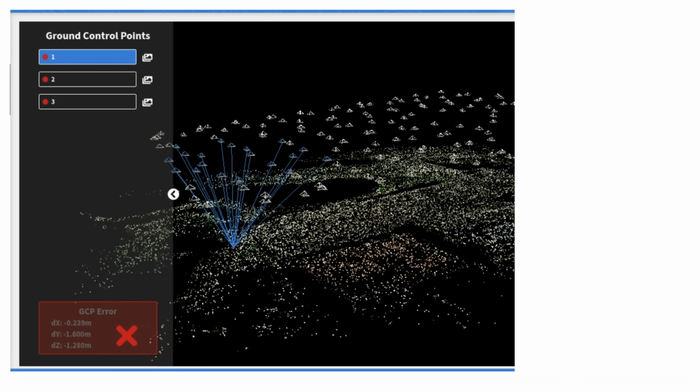What's going on here? Okay, and so that's why I say ground control points are so valuable, and checkpoints are so valuable, because they help you identify issues that you didn't actually know existed in your data. It looked great, but when you actually got down to brass tacks and compared it to existing surveys, you run into problems, and that's where having ground control points really helps out.